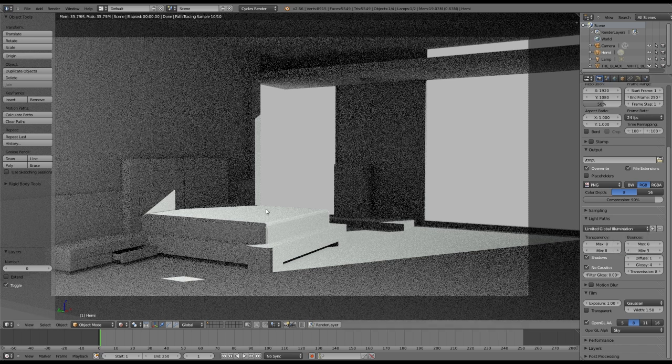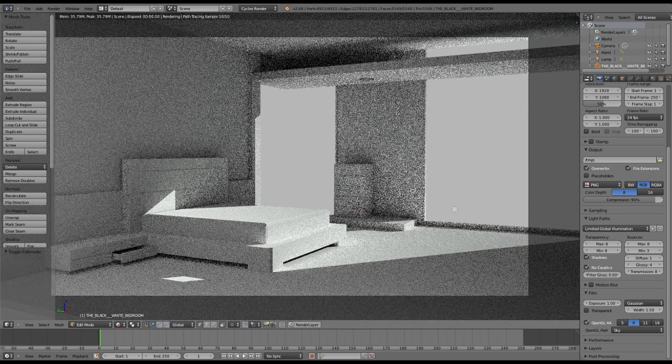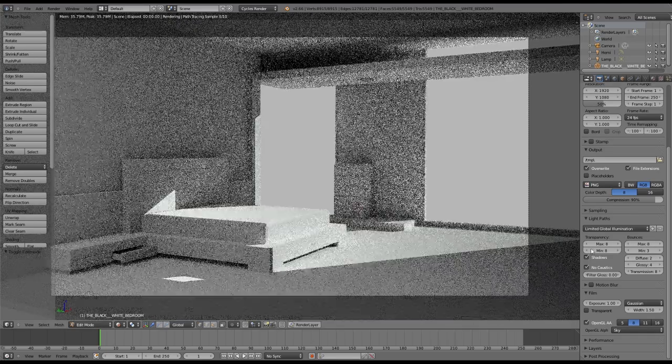I'm just going to press Tab again to refresh that. And that'll have light bouncing around the room, far more realistic, and it'll make materials look a heap better. If you want to manually change some of these settings, over here on bounces, the fewer bounces you have, the less time it's going to take to compute, but obviously the less light bounces around the room, the less good it's going to look. So I can change all those different settings.